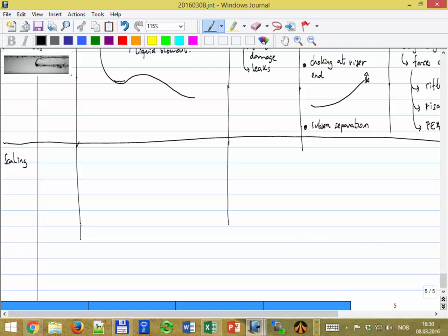It's, for example, brine water from the reservoir, and due to an equilibrium of the mineral, the solubility of the mineral in the water, it might come out of solution and deposit on the pipe walls. So we put that here: deposition of minerals from the produced water.